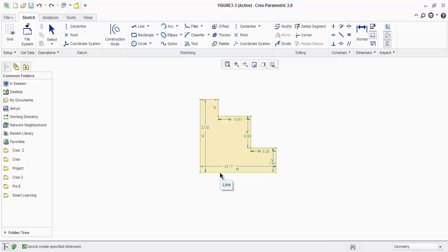So as you select this entity and use your middle mouse button, here you can add the dimension for zeros, that is this horizontal line has been taken as the horizontal baseline, and again you can click on this vertical line and you can use your middle mouse button to create the vertical baseline dimension. So these baseline dimensions are taken as the baseline references, so it is created as 0.0. So then you can come out.